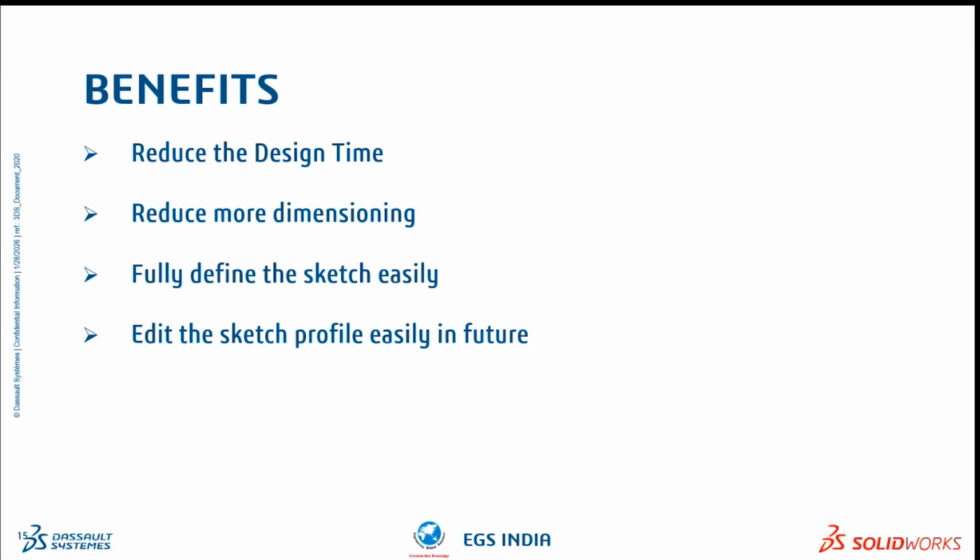How does this order help in our design workflow? First, it helps to reduce designing time because the sketch is created in a clear and planned way with less confusion and rework. Second, it avoids unnecessary dimensioning since dimensions are added after creating the shapes, keeping the sketch clean and easy to control. Third, adding dimensions and relations in the correct order helps the sketch become fully defined,